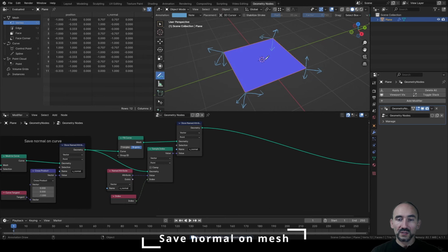The face orientation is pointing up, as you can see with the blue color, but this is wrong because next, when we are going to extrude the edges and move them inwards, and we are going to use a height to make a depth inside this shape, this face needs to point its normal down and not up, so not inside the final object, the pyramid, but outwards.